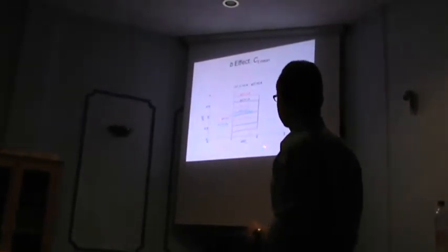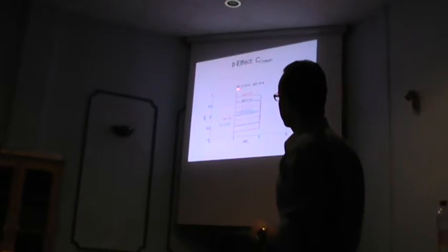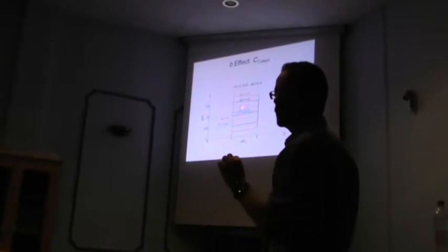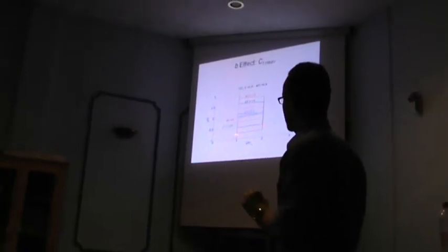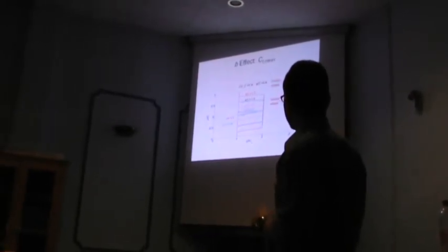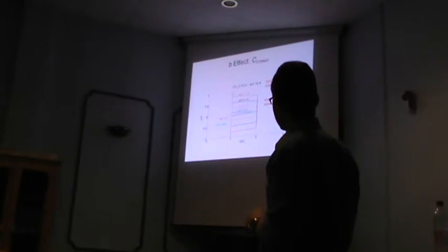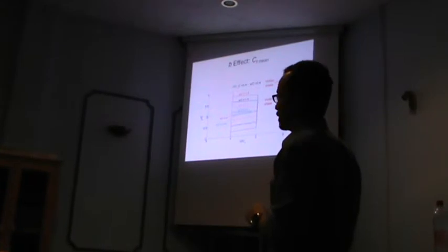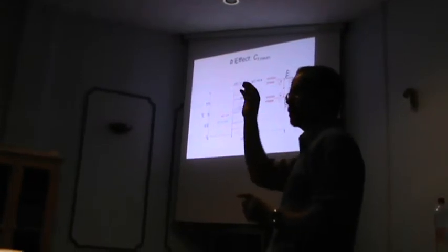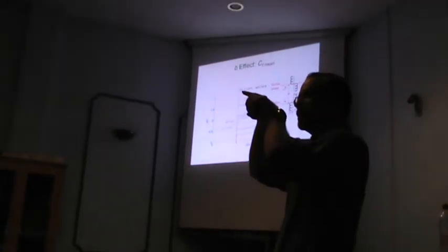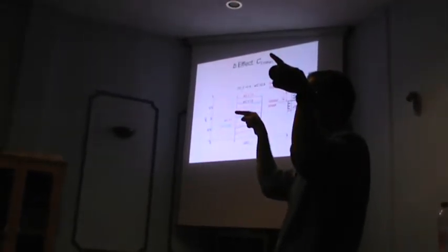Now, when you reach this condition, it looks like you have strong shear variation over a very thin zone on top and another one on bottom, with a uniform profile in between. And if you think about fundamental aerodynamics, you realize this essentially is nothing more than two vortex sheets. A vortex sheet is a different concept than a vortex. An idealized vortex sheet like this is a distribution of vorticity over a line.